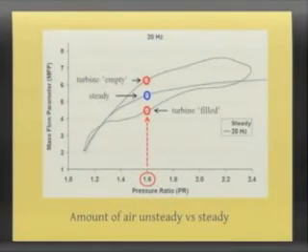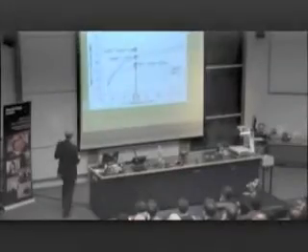So you don't follow the steady state. You have a state in which the turbine needs to be filled. So it is filled, and here it's empty. So it has to swallow more mass because that pipe, the manifold in the case of a turbine, needs time to fill up and then it needs time to empty. That's called a filling and emptying state. So really, mass flow, you would not match the steady state equivalent.